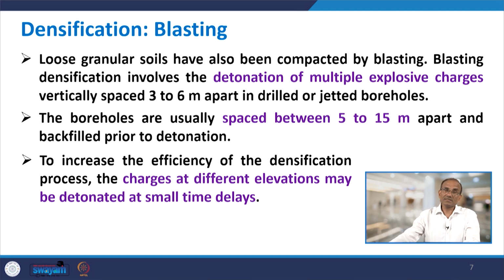In case of blasting, loose granular soils have also been compacted by blasting. As the name suggests, you basically use some explosive. Blasting densification involves the detonation of multiple explosive charges which are vertically spaced 3 to 6 meter apart, which could be in drilled or jetted boreholes. The boreholes are usually spaced between 5 to 15 meter apart and backfilled prior to detonations.